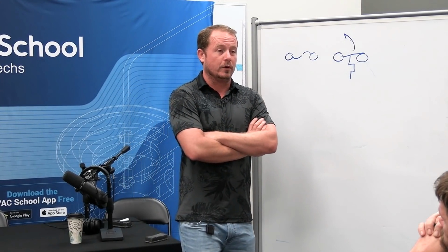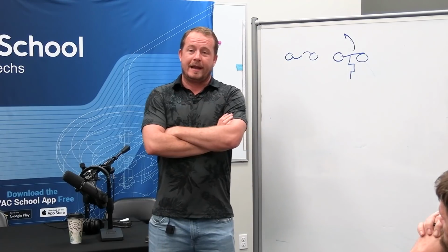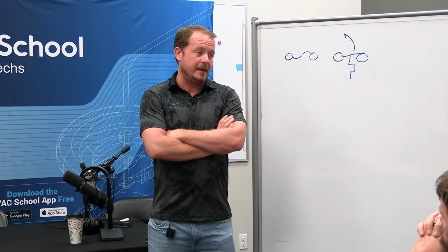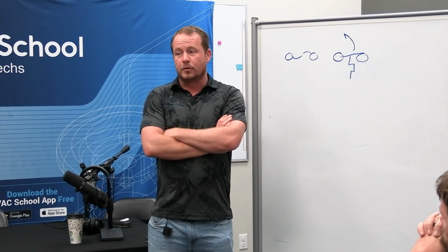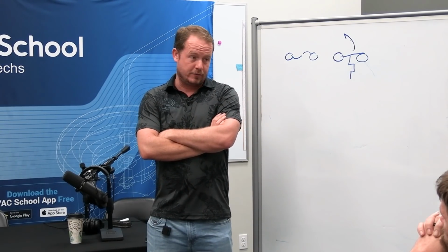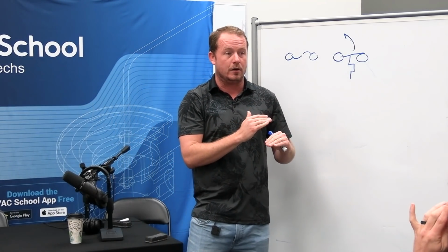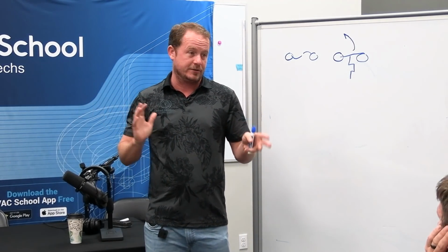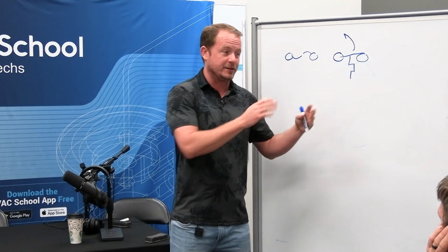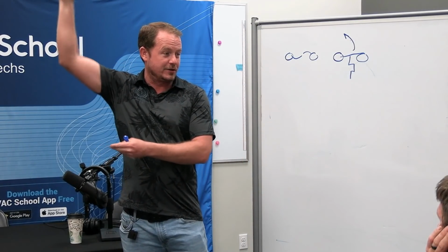Could be a condenser coil that is completely packed full. The reality is the compressor gets real unhappy when it has poor compression ratio. High compression ratio, meaning that if the head pressure is way too high or if the suction pressure is way too low, both of those things make a compressor unhappy. And the worst case scenario is if the suction's way too low and the head pressure is way too high.